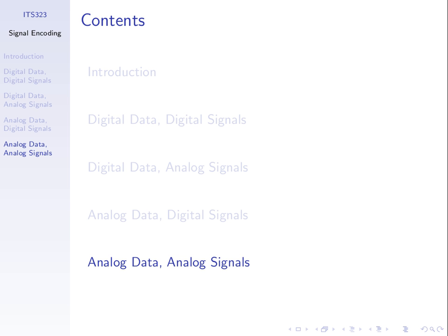And that's what a telephone line does. A home telephone line. The phone just takes the audio signals and converts it to an electrical signal to send across the cable within the same frequency range. So imagine the audio input is some sine wave or some waveform. What your home landline telephone does is takes that, because it's audio, it converts it to an electrical signal that's sent across the telephone line, and it's the same shaped waveform covering the same frequencies. So that's an example of an analog input sent as an analog signal. There's not much to do there, just convert the audio to an electrical signal.